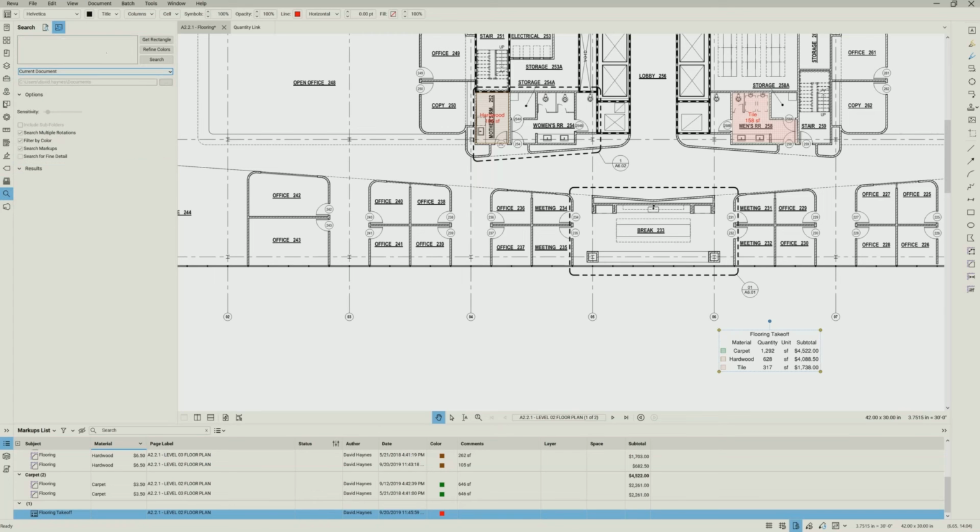This can be a time-consuming process, but you can see where David's at. Basically, you would drag a rectangle, or you can click multiple points if you want to get really precise. You would do a visual search for the entire PDF or a slew of PDFs, and Bluebeam's going to do its best and find elements that are of similar style. It does a pixel by pixel scan. It'll return a list, and then from there you can apply a count measurement to that. And sometimes if it misses one, you can edit the count measurement and manually add or remove a count if it picks something that was not correct.